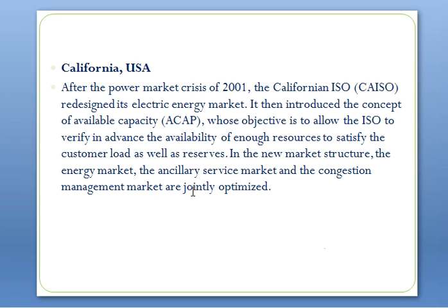The voltage control and frequency control. The voltage control in the California system: the ISO procures reactive power support service on long-term contracts from reliable must-run generating units. The actual short-term requirement is determined on a day-ahead basis after the real power market is settled and the energy demand and schedule are known.